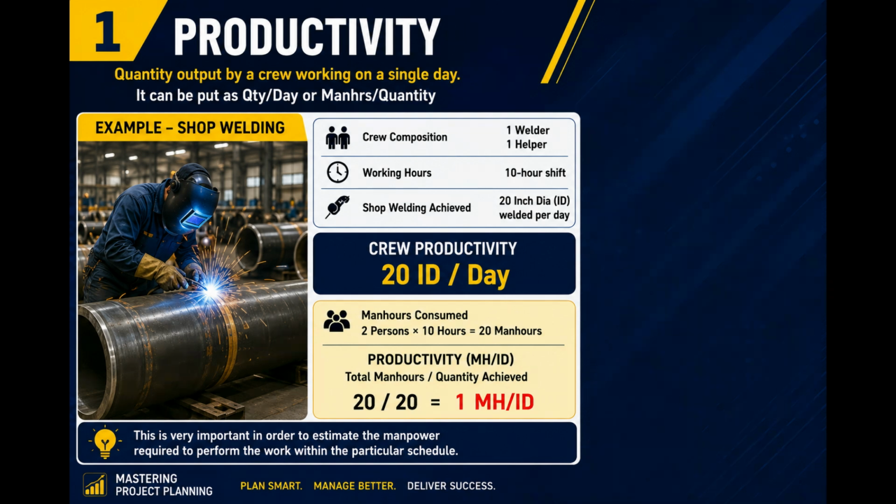So in planning terms, productivity is kind of a rate at which a resource, like your fabricators or your welders or your equipment like a crane, converts effort into completed work. So this can be termed as your inch dia per day. Inch dia is nothing but, if you're going to do some pipe welding, like welding an 8-inch pipe to an 8-inch elbow, then that one weld joint we call 8-inch dia. So we can say inch dia per day.